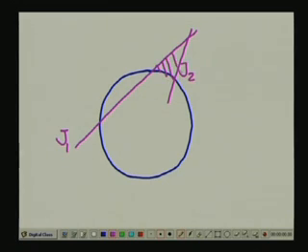Then you cannot always say whether this particular wedge is going to be susceptible to falling over into the tunnel opening, because of the frictional strength of the bottom surface of the joint and the dilatancy along the top surface of the joint, the strength because of dilatancy near the top surface of the joint.